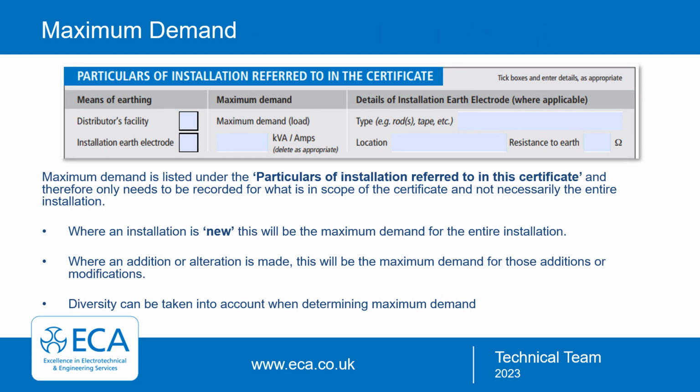When assessing maximum demand, this is listed under the particulars of installation referred to in this certificate, and therefore only needs to be recorded for what is in scope of the certificate, not necessarily the entire installation. So if you refer back to the extent of the certificate when you first started completing this form, where an installation is entirely new, this will be the maximum demand for the entire installation. If the certificate is for an addition or alteration, then it will be the maximum demand for those additions or modifications. You don't have to take into account the entire installation.